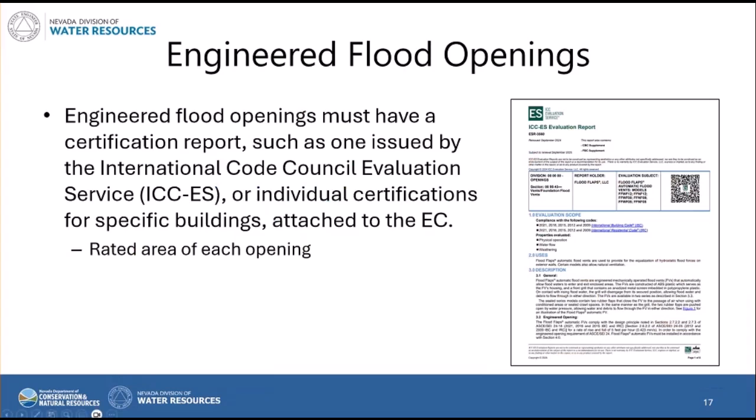If engineered flood openings are used on a building, it's important to make sure that that ICC-ES evaluation report is attached to the form.